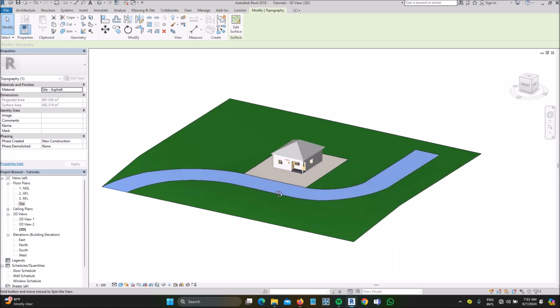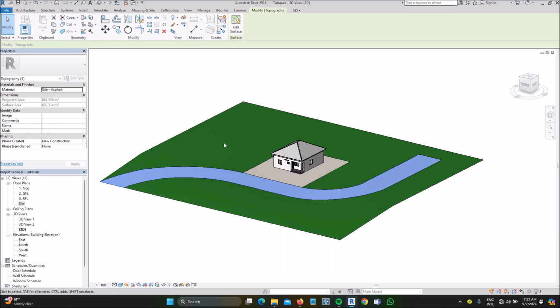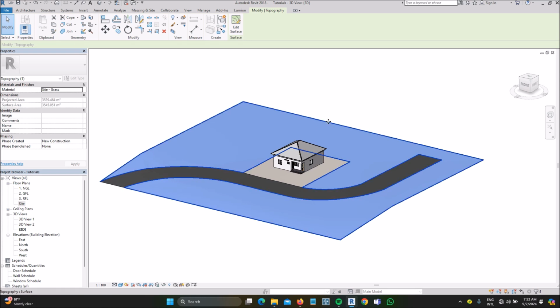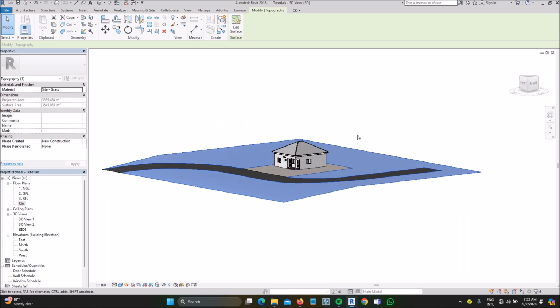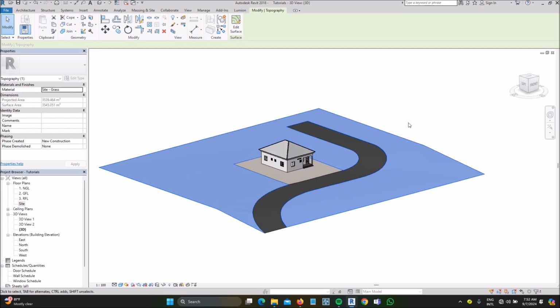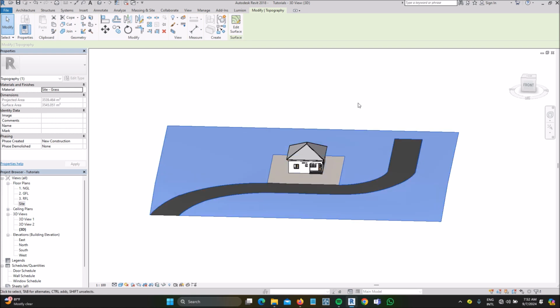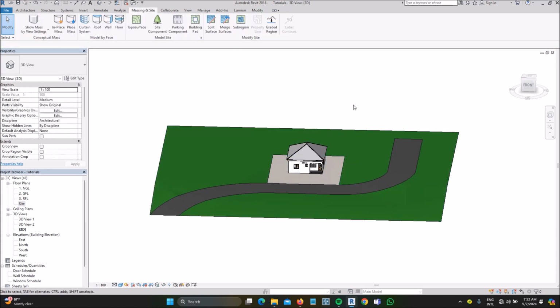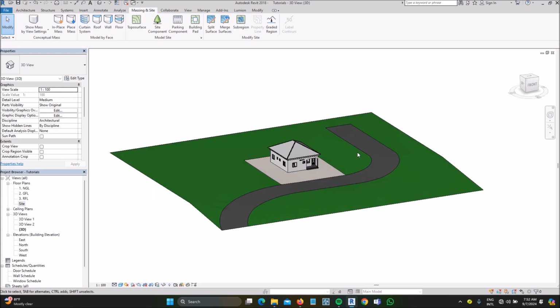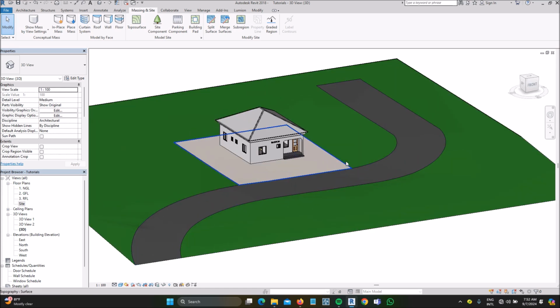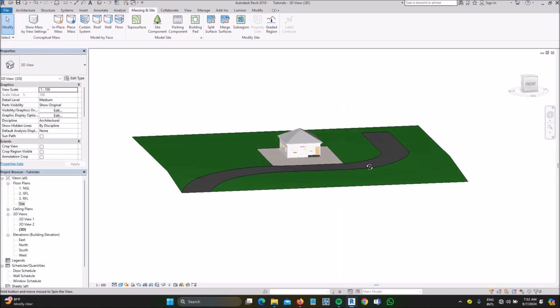So one thing you must know, one rule is that you must make sure the main topo you have created, you don't have any errors on it. Because once you start splitting, if you see any error, you have to cancel all this and start all over. So you have to make sure that you get the main topo surface right before you split. So alright, so the next thing you need to do, if you need to make this a solid, I will just explain with maybe one or two, then we'll get that done.